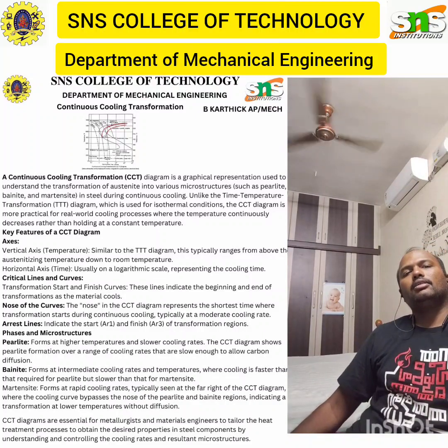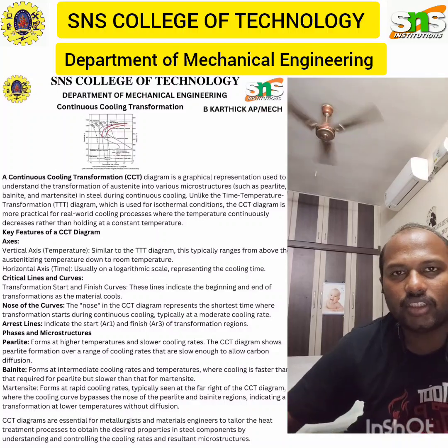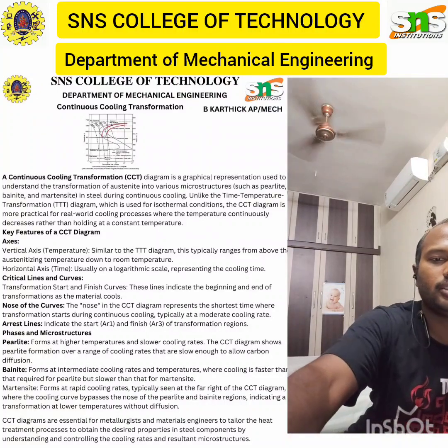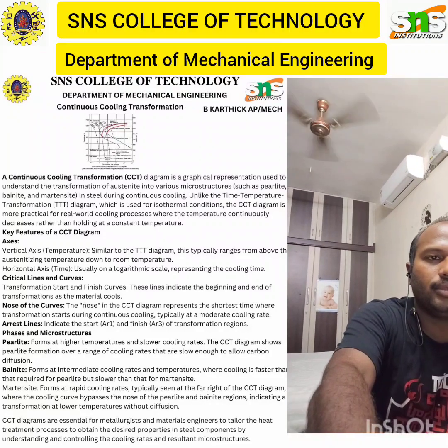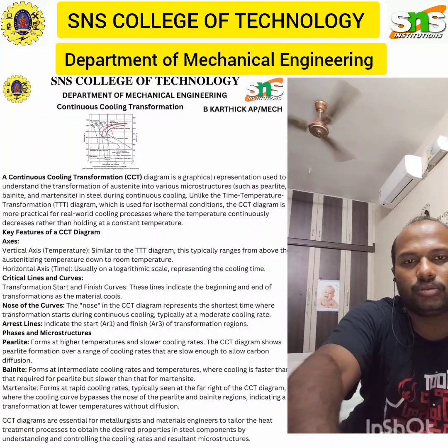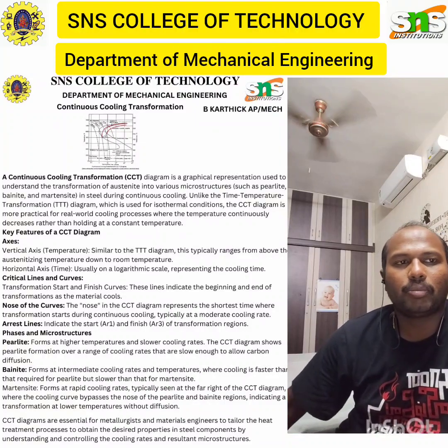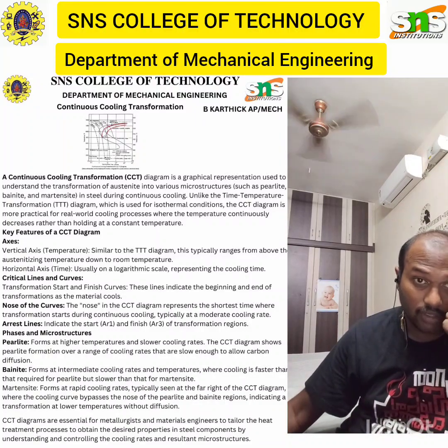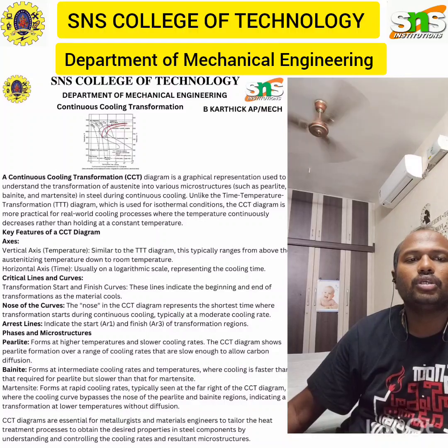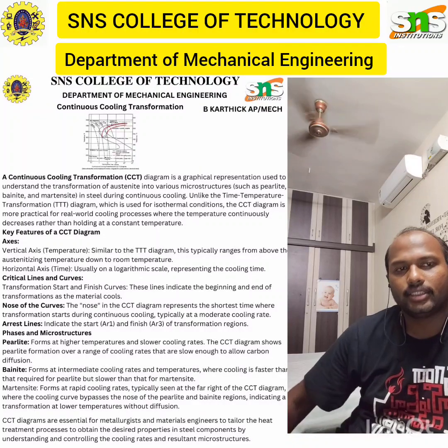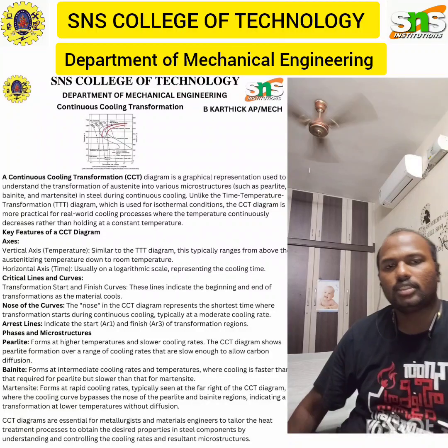And critical lines and curves, the transformation start and finish curves. These lines indicate the beginning and end of a transformation as the material cools. So the nose in the CCT diagram represents the shortest time where the transformation starts during the continuous cooling, typically in the moderate cooling rate. The lines indicate the start Ar1 and finish Ar3 of transformation regions.